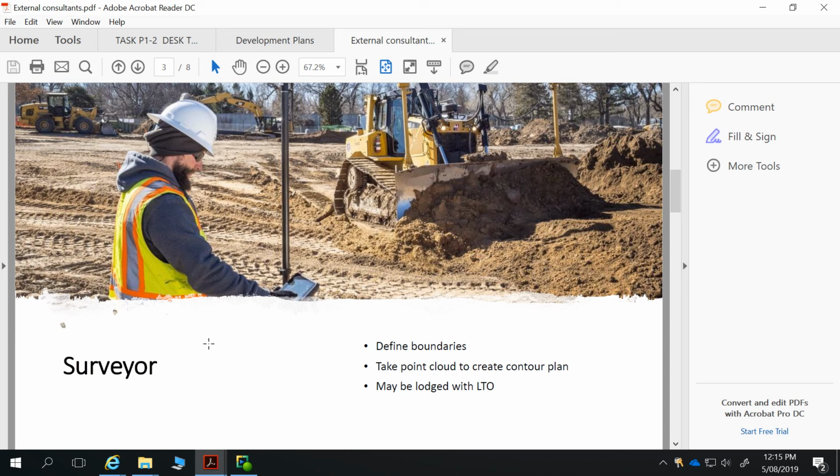Whereas there's now that technology, and you can hire one of these instruments, go out, take points about the place. Once it's talking to the satellite, taking your points is really easy. Get that point cloud. I don't know what program you use, but that point cloud can then talk to a program to produce really accurate, detailed contours.